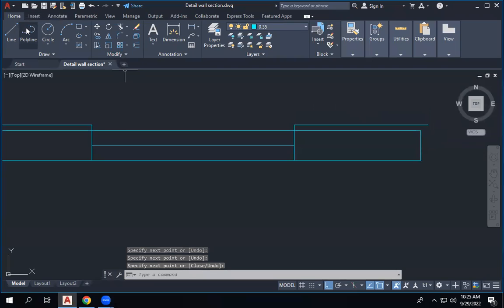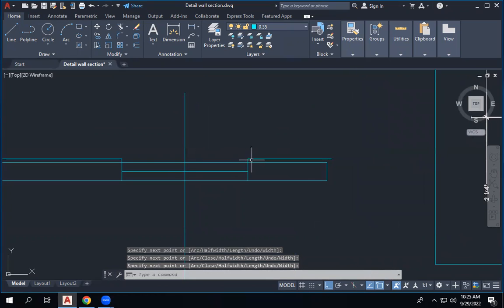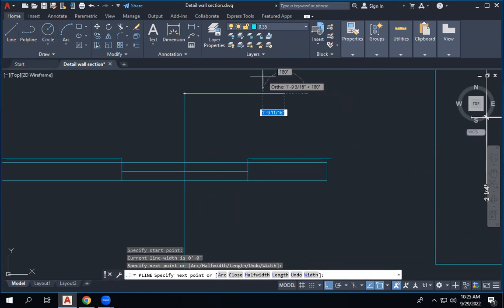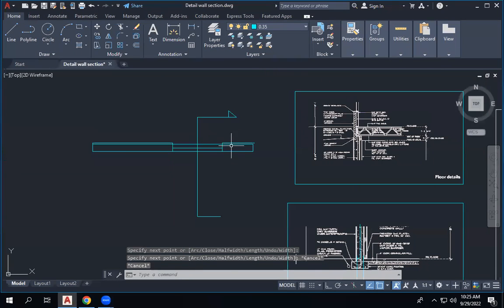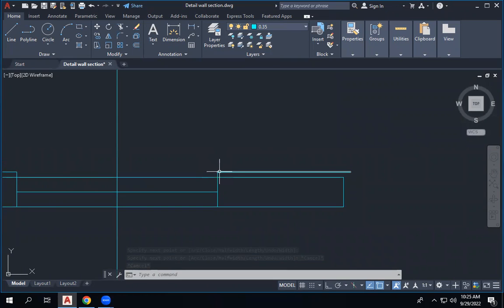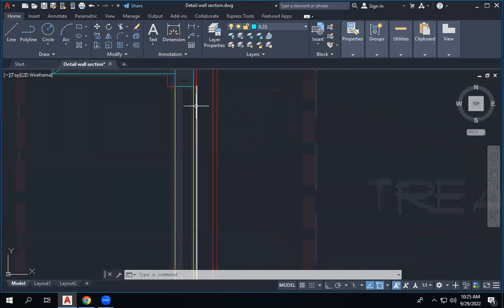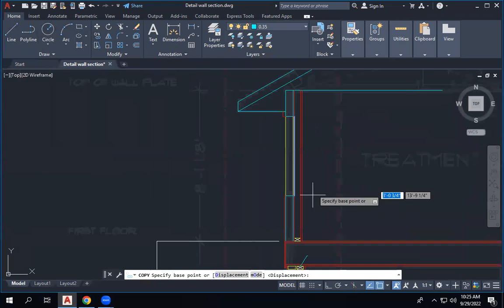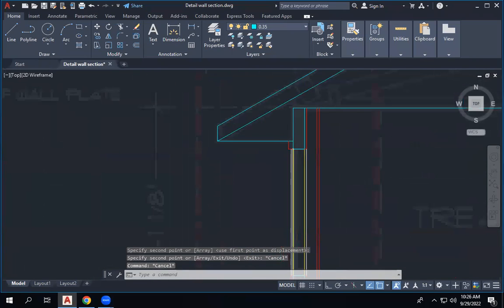So if I section it here, what do you see? You see this portion in section. That's the line I drew there. You're looking at this way. But it should be in a lighter color because it's in projection. That's why I make it 0. Right. It will be the same thing here. This side, also in this lighter line thickness.